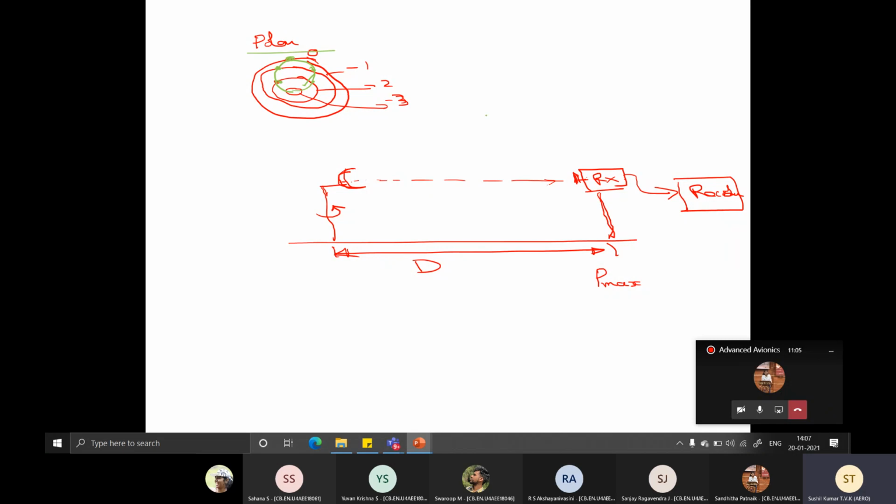The other way is using normal Cartesian coordinates, in which the same information is represented with the y-axis as power and the x-axis as angle. You plot from 0 degrees, 90 and so on up to 180, and in the reverse direction -90, -180. When you take the reading for 0 degrees, that is exact alignment between the transmitter and receiver, the antenna is looking exactly at the receiver. Then you get maximum power, so you note down that maximum power.